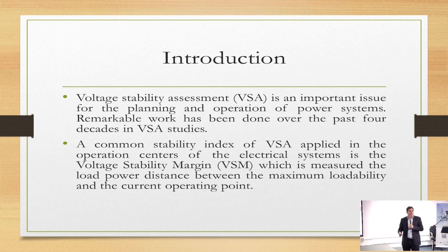I've shown you the concept of voltage stability margin in my previous presentation. But this stability margin is a function of the defined load growth. And actually, the direction of the generation growth also matters for calculating the voltage stability margin.